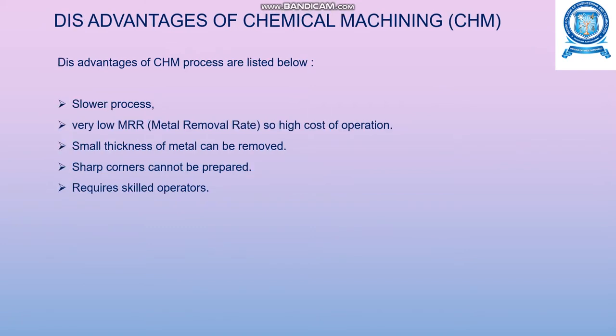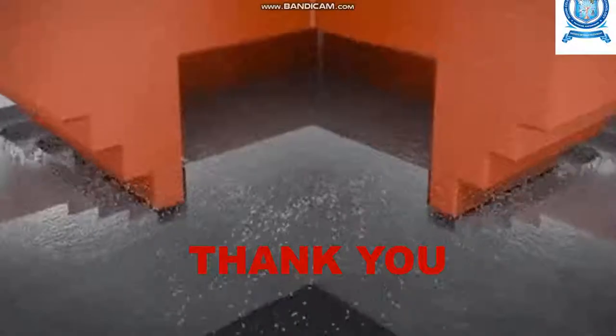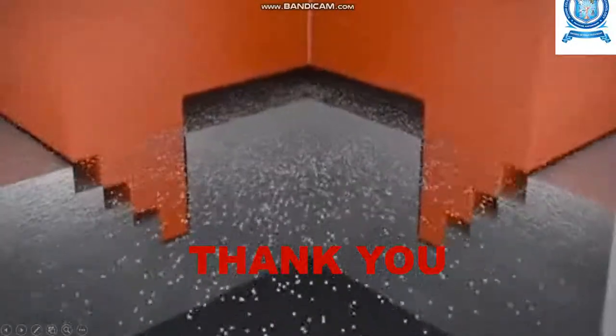The disadvantages are that the process is slower, and the metal removal rate is very low, so the cost of operation is high. Only a small thickness of metal can be removed, sharp corners cannot be prepared, and skilled operators are required. With this, we come to an end of this introduction part of the third unit.